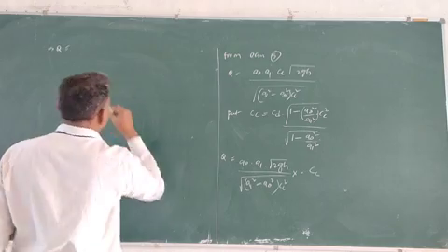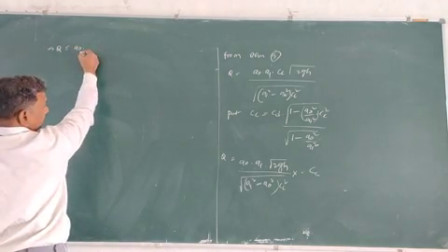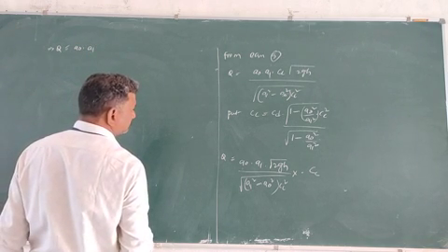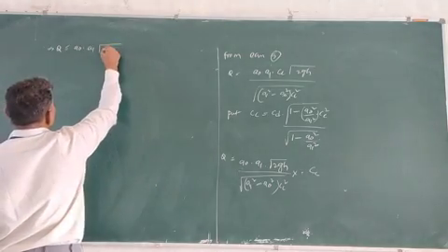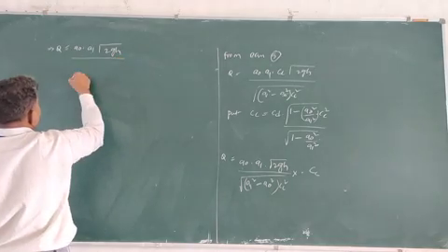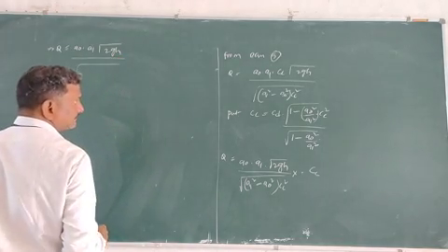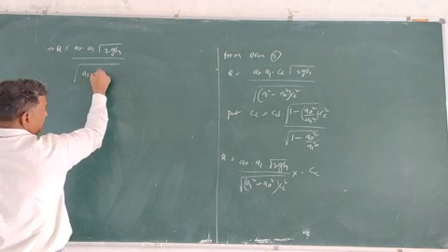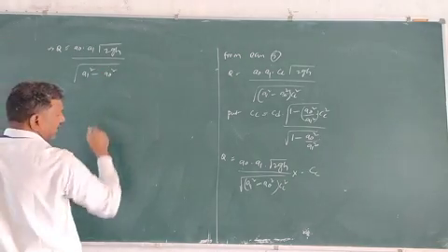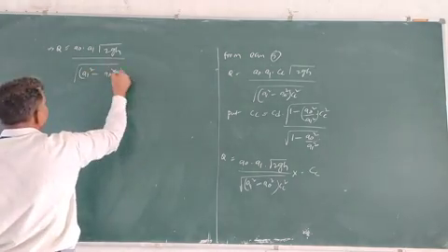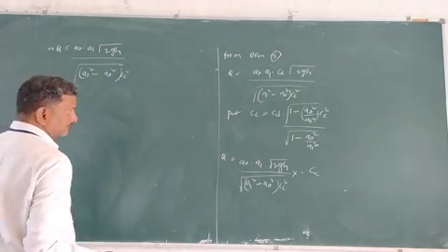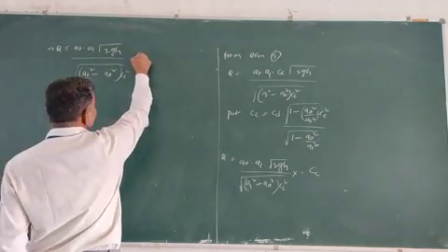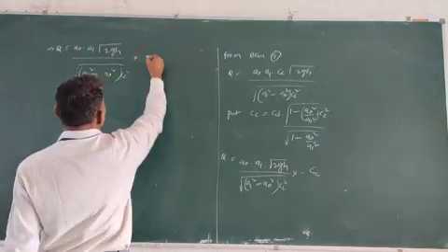Q is equal to A0 A1 into square root of 2gH divided by A1 square minus A0 square into Cc square, into what's the value of Cc?